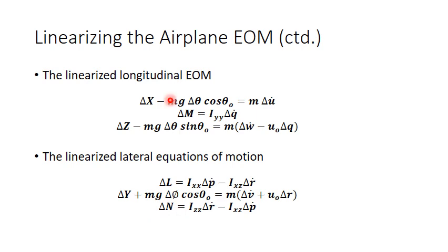And for these three equations, the first one represents the x-force, which we discussed in detail, and the second one represents the pitching moment equation. So this is the rotation about the y-axis, and the third one represents the z-force equation.